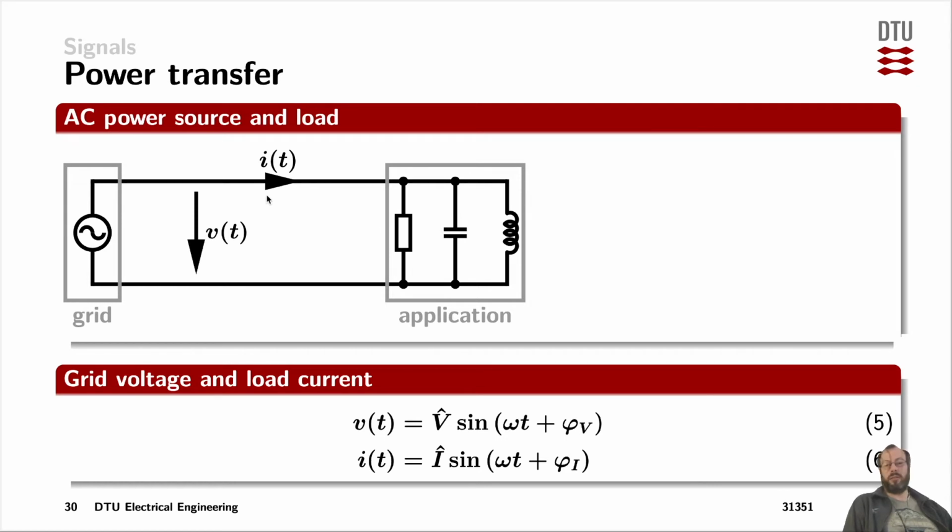A major disaster would come if you actually change the direction halfway through your calculations, and all of a sudden the assumptions that you made, the initial equations that you wrote down about a circuit, would not be valid anymore because you're changing the direction of a voltage or a current along the way. So I'm defining it as a positive voltage up here. Up here, that's the positive end of a voltage, and that's the negative, even if the value of Vt might be negative in some parts of the time or even all the time. The current is flowing from the left to the right as a positive definition.